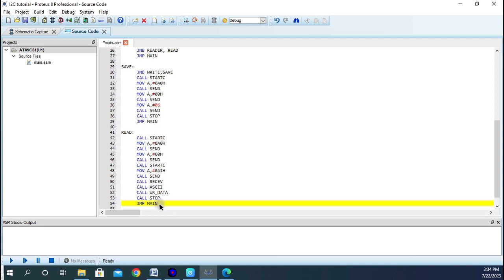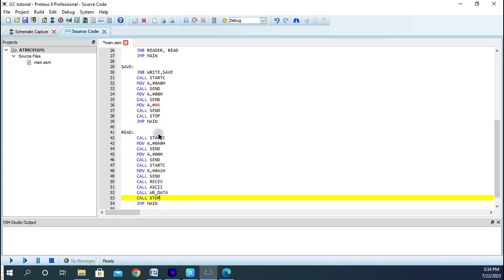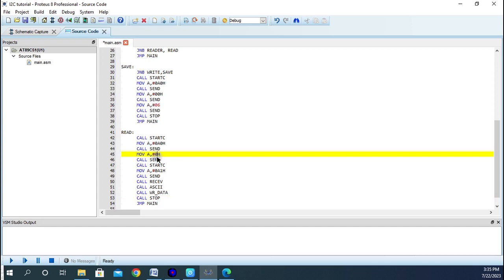This is the code for reading information from I2C. If we save on 00H and you now want to read from 05, you will not get anything there because your information is not on 05, it's on 00H, the first memory location. So that is where we read.